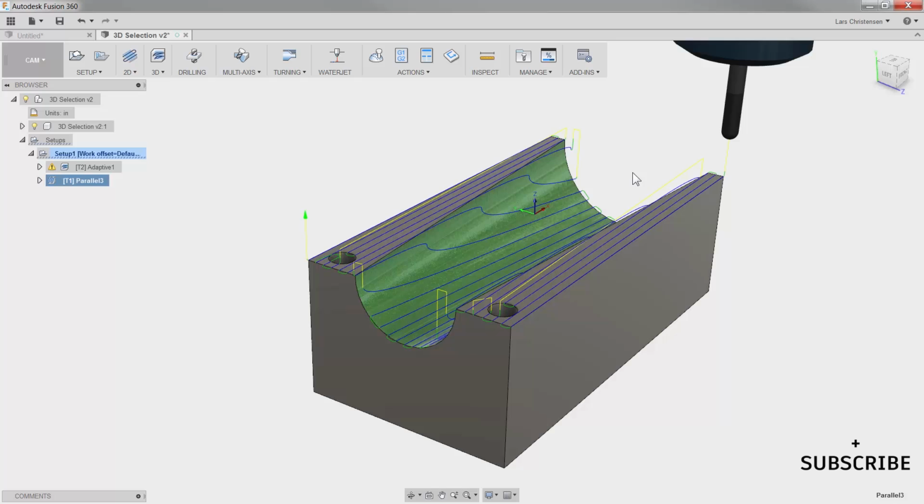One of the major differences between a 2D toolpath and a 3D toolpath within Fusion 360 is that in a 2D toolpath, you will pick all the geometry to get something to machine. But in 3D machining, it has already been selected. What we're going to do from here on is adjust the toolpath. So that's why you just select your tool, hit OK, and see what you get.